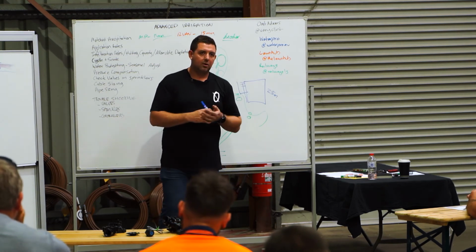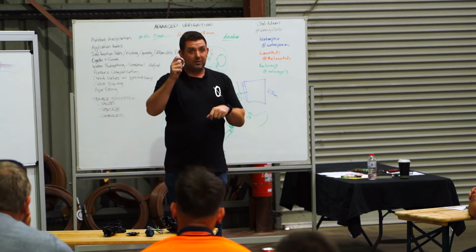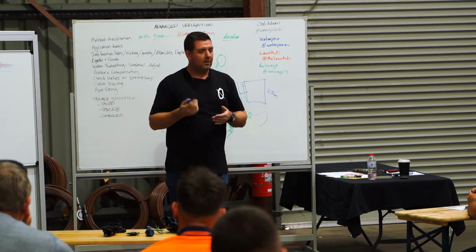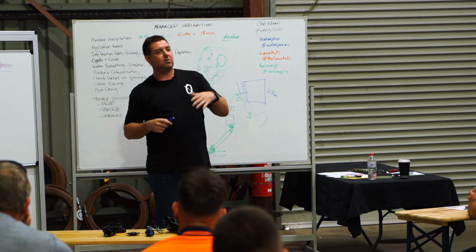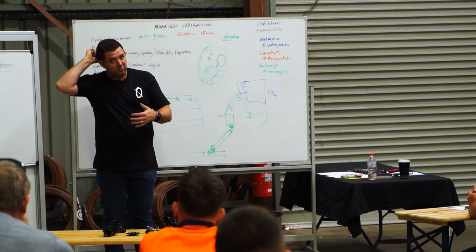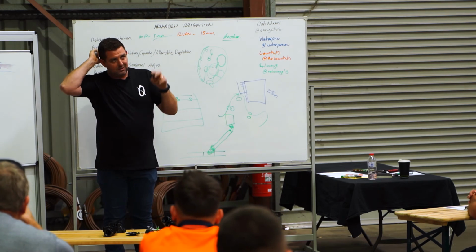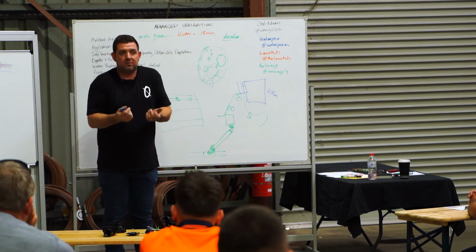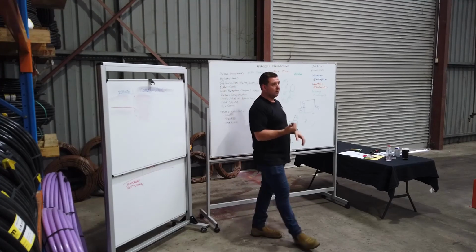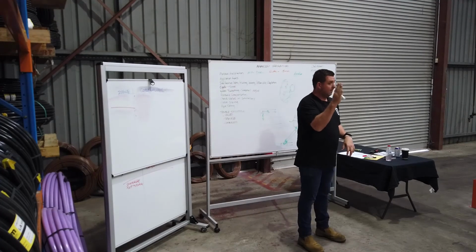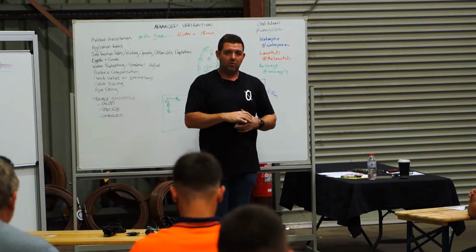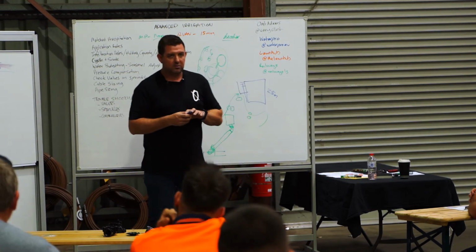Yeah, so modules. A lot of controllers come with modular expansion, and sometimes you'll have a situation where you put a new module into the controller but the module doesn't work. It's recommended by all manufacturers that when you install another module for more stations, you give the controller a hard reset and program it from scratch. The controller won't necessarily understand that it's received that module until it's been reset. I don't know what process it does inside its computer where it goes, oh, okay, new software, new hardware, and it understands it. But if you're having trouble with a controller module, it might not even be that module that's not working. You might put a new module in and the whole thing stops, or the power module stops. Every time you have an issue with your controller, before doing anything else, reset the controller and start from scratch.